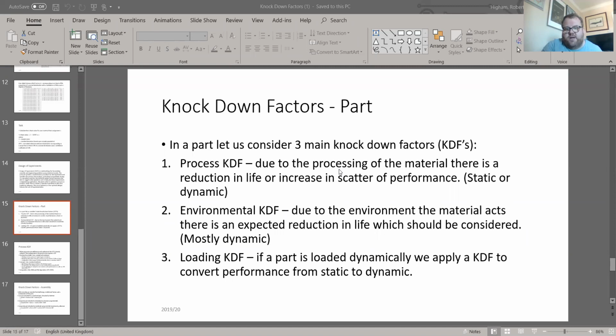So for example, we go back to that upright example, always exposed. Titanium's much better at resisting corrosion than aluminium. Aluminium, when it's close to other parts, as we'll talk about in the next couple of slides on assemblies, can have a lot of issues. So what environment is the thing operating in? Very high temperatures, low temperatures, cyclic temperatures, all of those things have to be considered because, again, different materials act differently in those conditions.